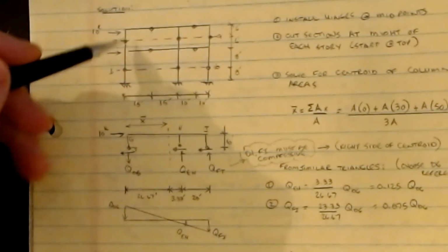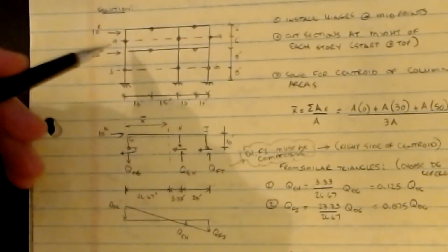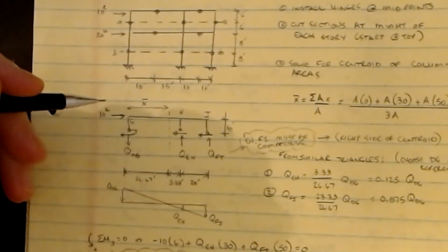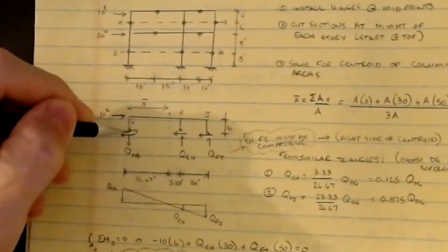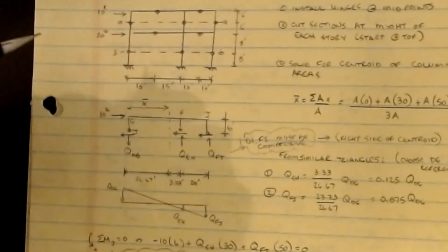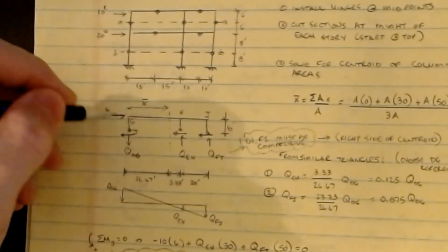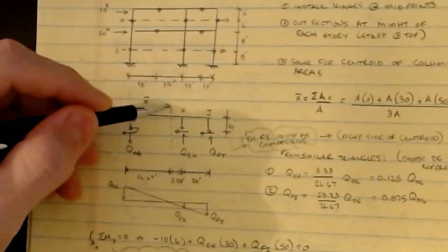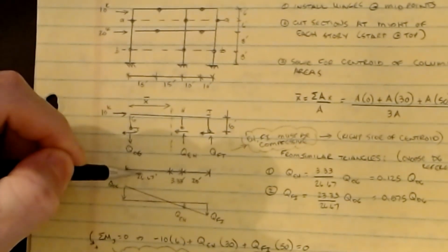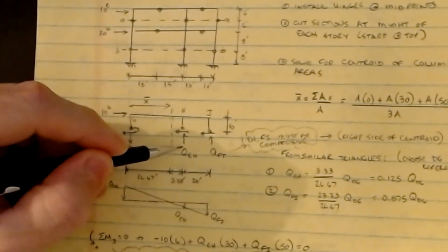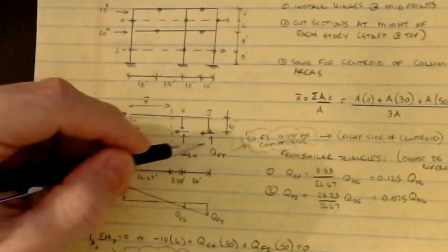Now we're going to take our beam, look at just the top floor, and work our way down. So here's the free body diagram. If I cut it at the hinges, there is no moment at the hinges. That's why we put them there, and so I have 2 reactions at each hinge. Then I have my 10 kip force on this point. The other one doesn't show up because it's on the piece down below. My x bar, this dotted line, is located 26.67 feet, which means that from here to here is 3.33 feet, and then it's another 20 feet to this one.